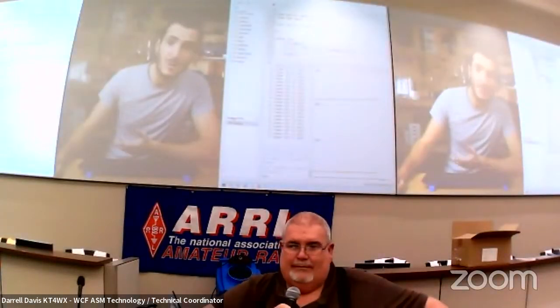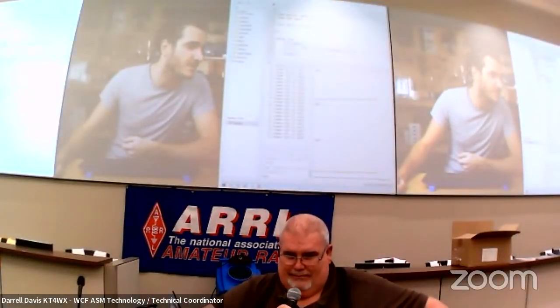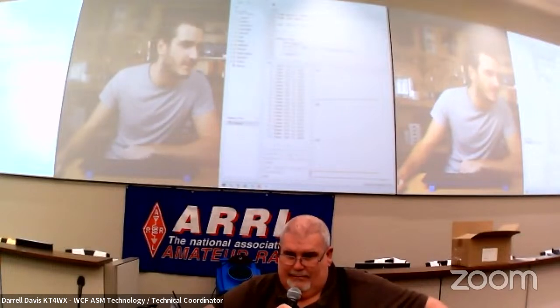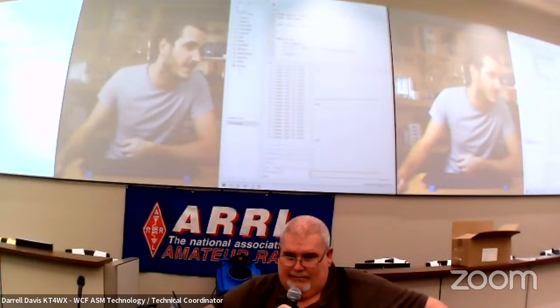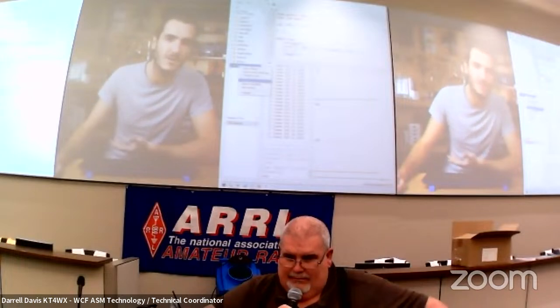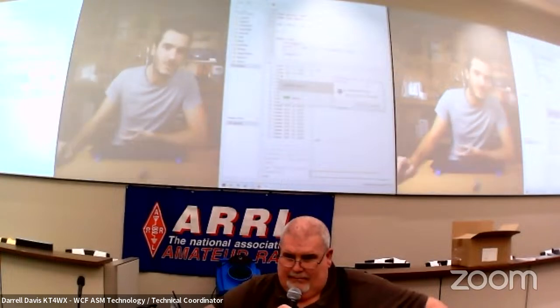So we've been saving our scripts directly to the Pico so far, as you can see in the file tree here. If you want to create a backup of that on your computer, you can right-click and select download to my user home directory, and then you can put it wherever you like. Also, the scripts that are on your computer already, you can right-click them and select upload to, and that's the root directory symbol. So that will upload it to your Pico, and you'll get a warning that it's going to overwrite the same file on your Pico.